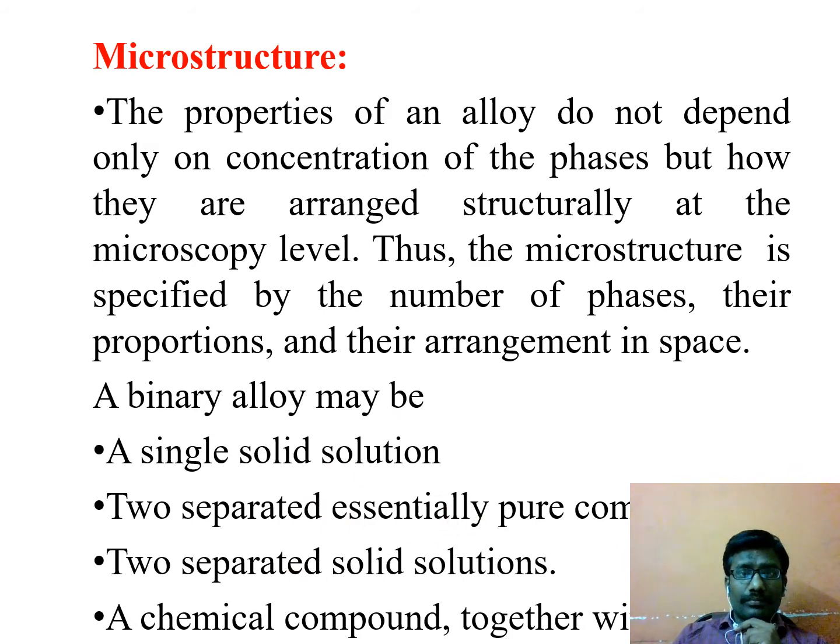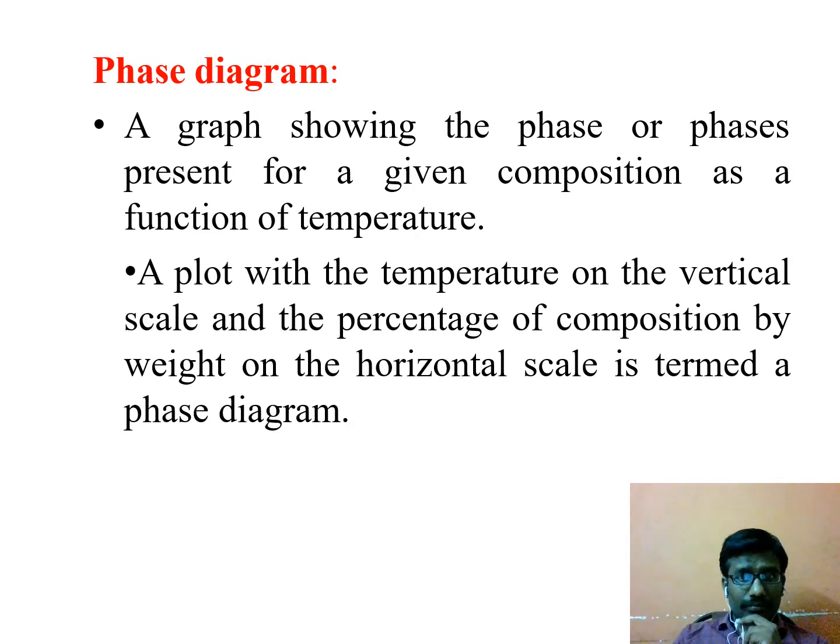So this is about microstructure. Next, phase diagram. A phase diagram is a graphical representation of various phases for a given composition with respect to the temperature. Here on the y-axis we have the temperature, and on the x-axis we have the composition of the alloy, and pressure we are considering as a constant atmospheric pressure.